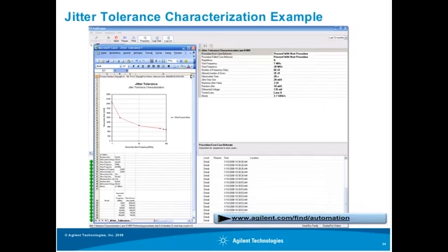And there's one example on the next slide, which is a jitter tolerance curve. So this curve looks maybe very similar to the jitter tolerance curve given in the standard, which I had on my slides before. However, this is the same curve, but it's the measured limits of a product. And now you can compare those measured limits of a product against the specification. And you can also find weak frequencies, but in this example, everything looks pretty well.